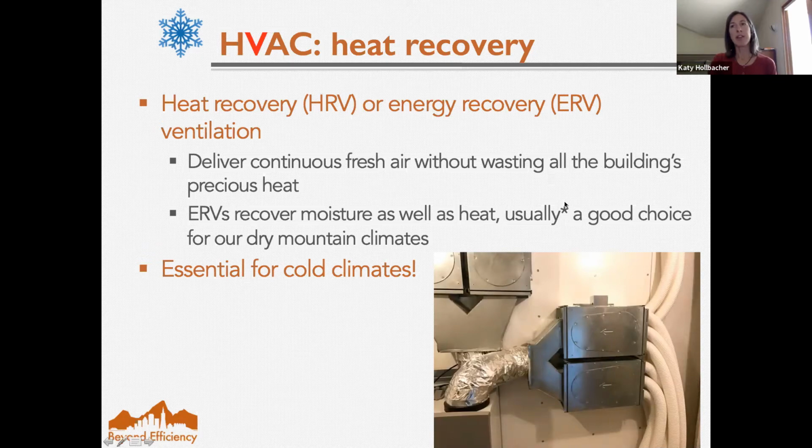And the little asterisk I have here: generally, as a default, I feel ERVs are a good choice for our cold, dry mountain climates, because in the winter, when everything gets really dry, you want to keep that humidity in. But again, you always need to think about the situation. What is the particular space you're designing for?